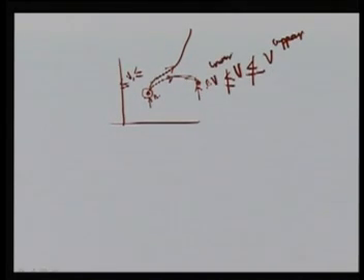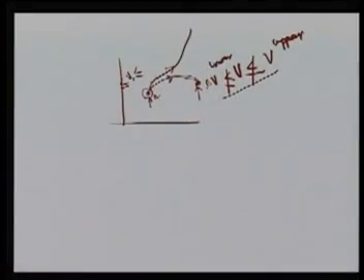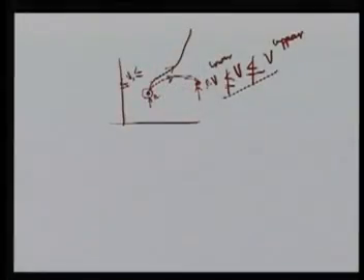So, the system is stable, but it is violating the operating constraints. In this case, I have taken the voltage. It may be your line flows, overloading of the line, or a violation of the reactive power limits, and so on. So, this point is stable, this point is stable. In terms of stability, we can say our system is stable, but in terms of security, this point is stable, but the system is not secure.